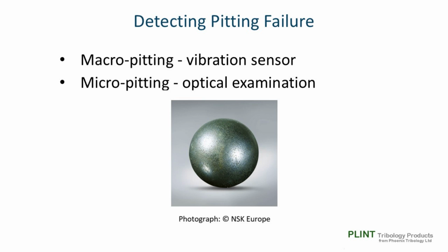Another yet unproven method of detection that does not require direct observation of the surfaces is to use low ohmic value electrical contact resistance measurement to detect changes in conductivity of the contact. The assumption here is that the presence of micropits may increase retention of oil on the bearing surface, resulting in a small change in conductivity.